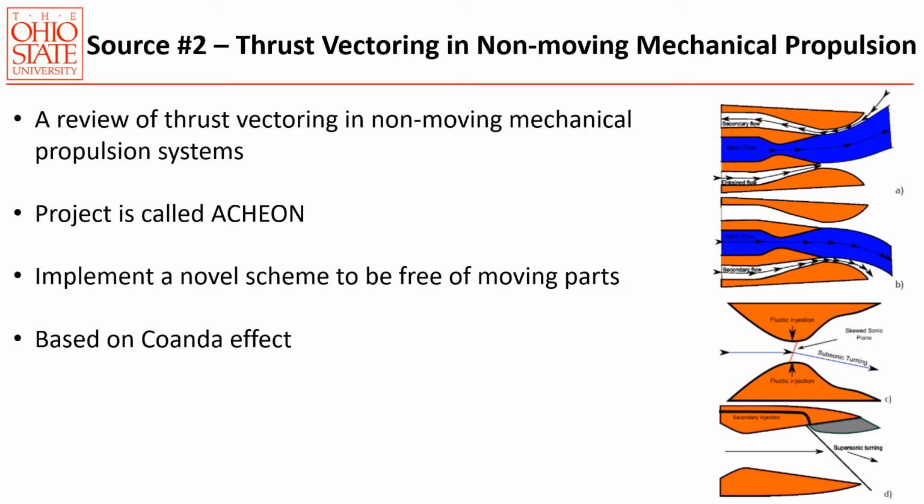For those of you who don't know what the Coanda effect is, it is the tendency of a fluid jet to stay attached to a convex surface. In the counterflow arrangement seen in Figure A, vacuum is provoked on a slot that is surrounded by a suction collar around the main flow. A stream of reverse flow is created near the wall, and an effect similar to the co-flow system entrains the main flow. Seen in Figure B, we can see a low pressure is generated by means of adherence of a secondary flow to a curved surface, also entraining a deflection of the main flow.